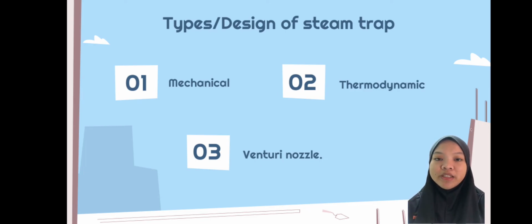Secondly, thermodynamic steam traps. Thermodynamic traps are durable and have a straightforward operation. They are used in applications where flash steam must pass through the trap. Water hammering and vibration have no effect on thermodynamic traps, which are used for high pressure and superheated steam. These traps tend to discharge a large amount of air on startup if the inlet pressure gradually builds up, and will not work positively at very low differential pressures because the velocity of flow across the underside of the disc causes lower pressure to occur.